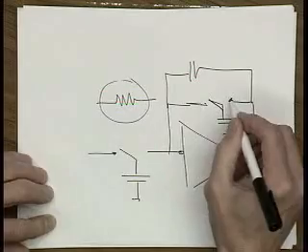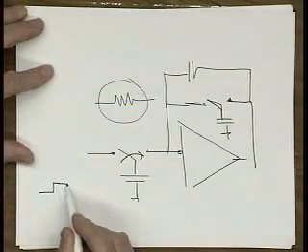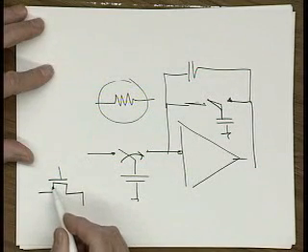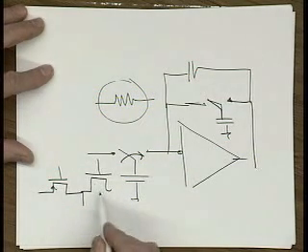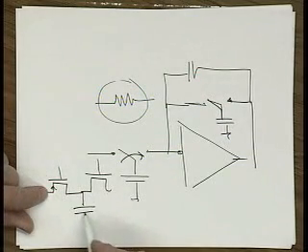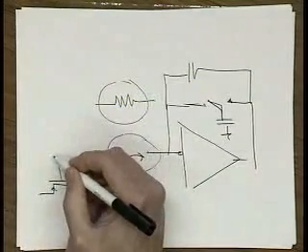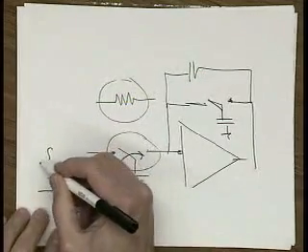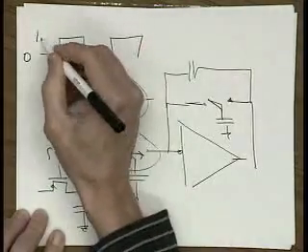So what is this little thing right here? The real circuit of that is this. It's two switches that go between, and we don't even actually know which is the source and drain. They're actually operated off and on. So this circuit right here has two clocks associated with it, and what I mean by that is it goes between 0 volts and 1.2 volts.